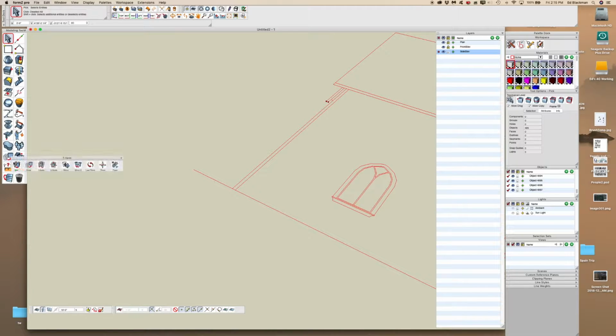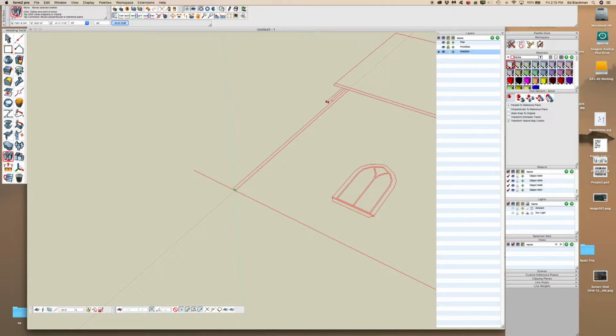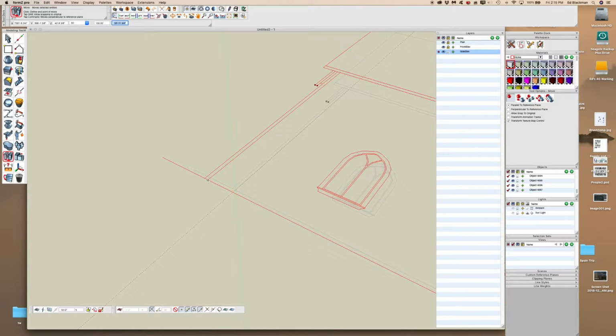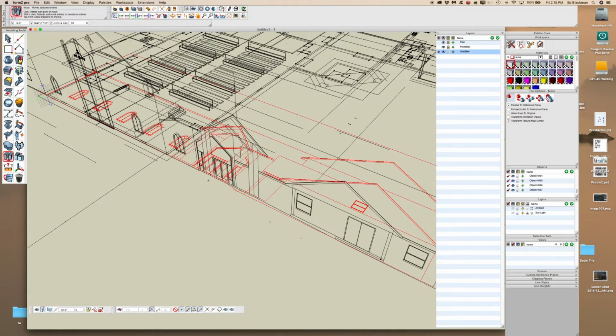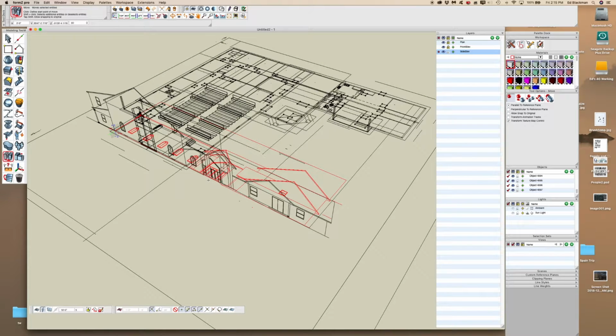So we'll go down here and select the Move tool. Come over here and click on the corner. Just start the move and then go up and tab. And you'll see at the upper left-hand corner, 0, 0, 0, and then hit enter. And then do Command F to fit. And you can see that elevation has flopped in that corner. So that corner is locked up.